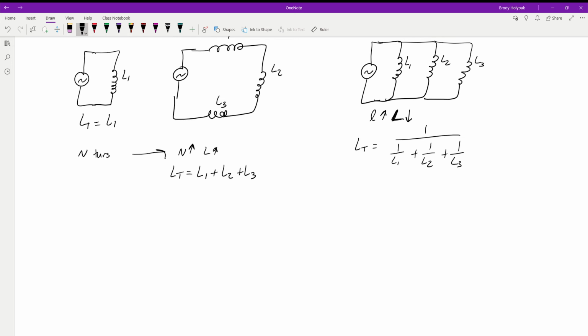So the opposition to the AC current, the opposition to the change in AC, that's what we get our reactance. So remember, last time our X of C value, for capacitors, was 1 over 2 pi times the frequency times the capacitance. Well, when we're talking about inductors, X of L, the reactance of an inductor to AC current, is equal to 2 pi F L. So just a slight variation on that. And this is also in relation to the more inductance we have, the more reactance we're going to have. We're going to see an opposite effect of these guys.